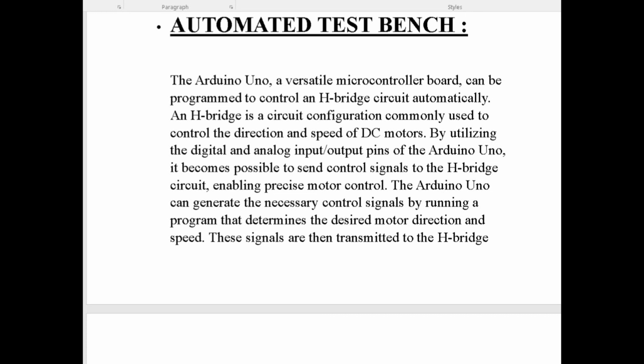Now, from Arduino, you're going to send control signals to the H-bridge circuit, enabling precise motor control, meaning controlling the motor according to your need, moving it clockwise or anti-clockwise. The Arduino can generate the necessary control signals. The main purpose of Arduino is to generate control signals that are sent to the circuit.